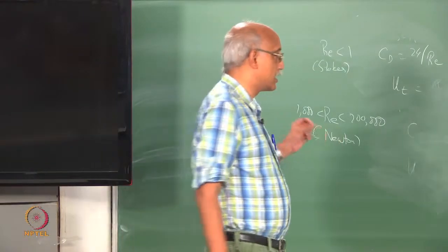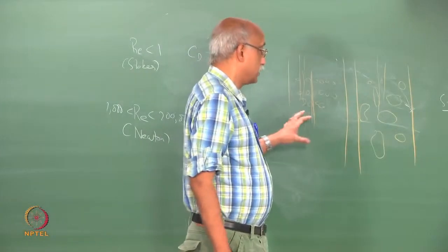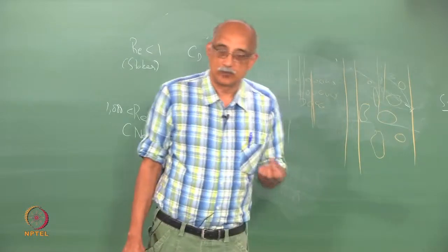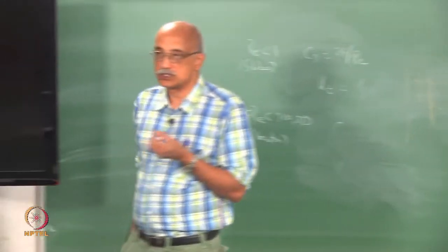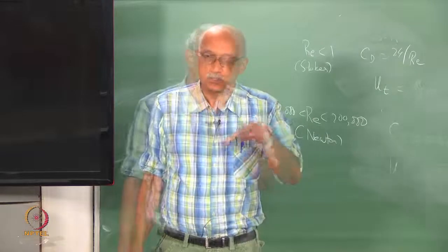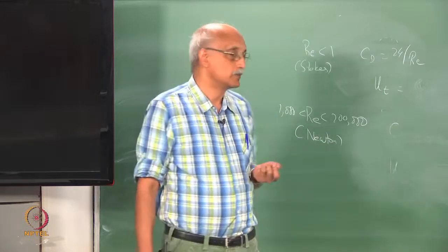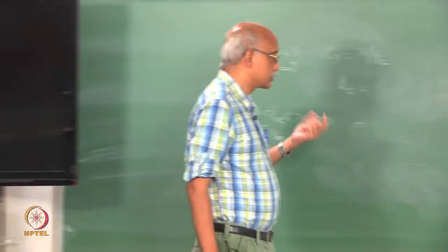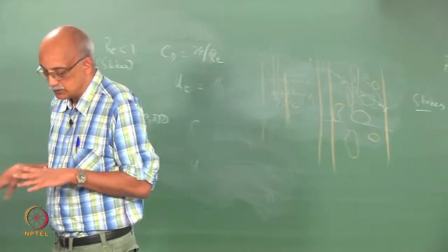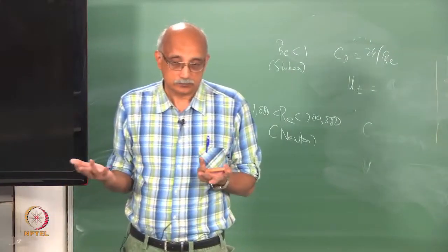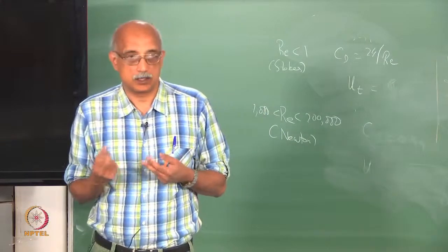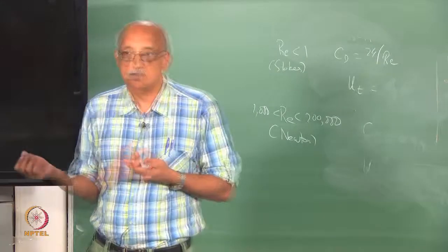So a lot is now going to depend on whether there is sufficient room and sufficient time for particularly the non-spherical particles to achieve different orientations and thereby present different areas to provide resistance to the fluid flow. Also, if you look at the size characteristics, in which size range would shape have a greater effect? Would shape play a greater role if you have very fine particles, or would shape play a greater role if you have very large particles? Any ideas?